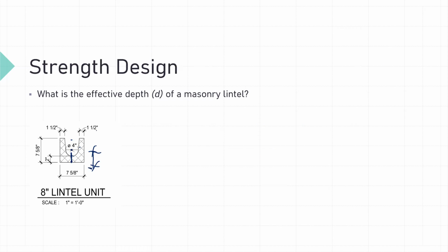And these closed shape units, again, only typically come in gray standard type units, because if we need to split the unit for like a split face architectural unit or a burnished unit, usually the manufacturing process is going to be too hard for us to actually make a closed bottom lintel unit.